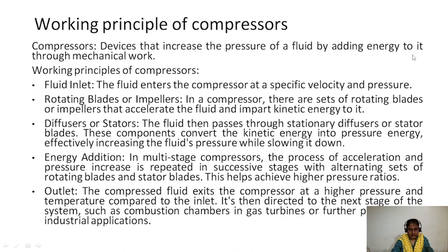Now finally, after all this energy addition, the fluid will exit the compressor at a very high pressure and temperature compared to the inlet. It's then directed to the next stage of the system, such as the combustion chamber in gas turbines or further processing in industrial applications.